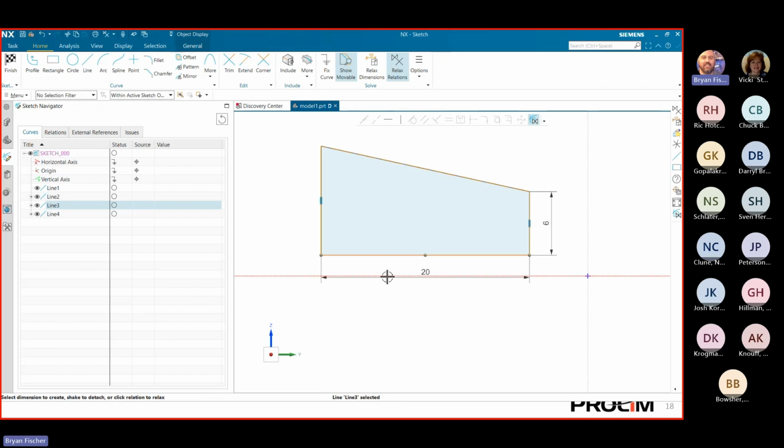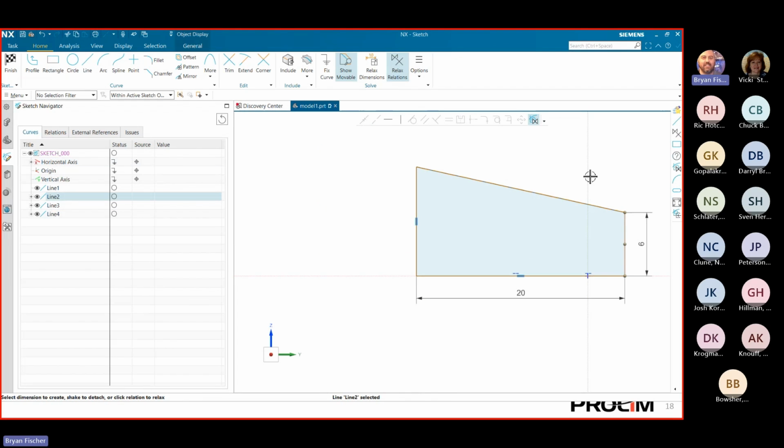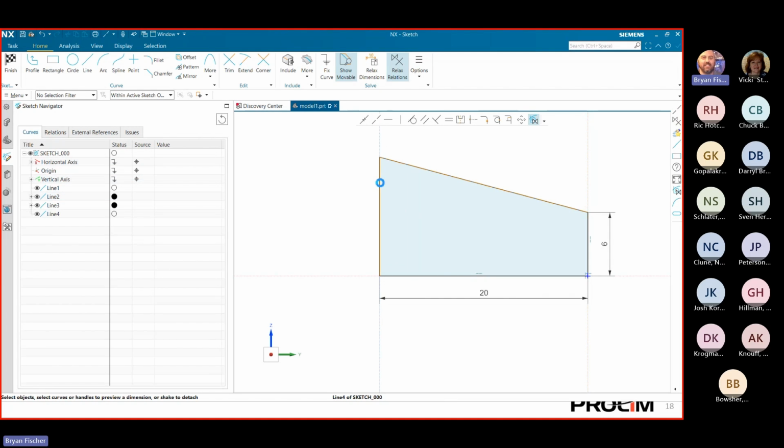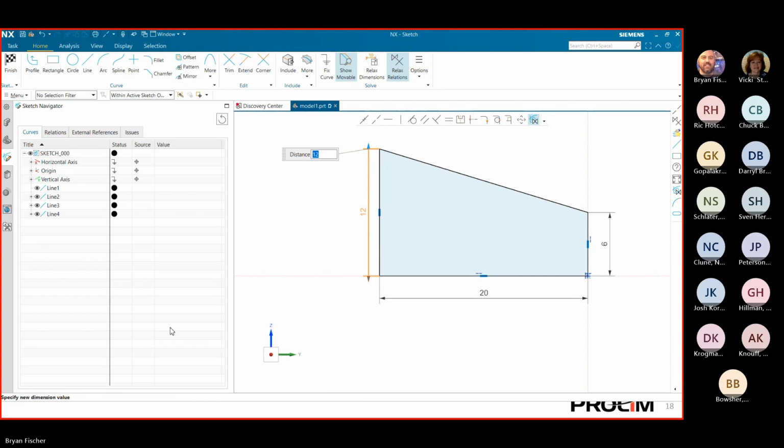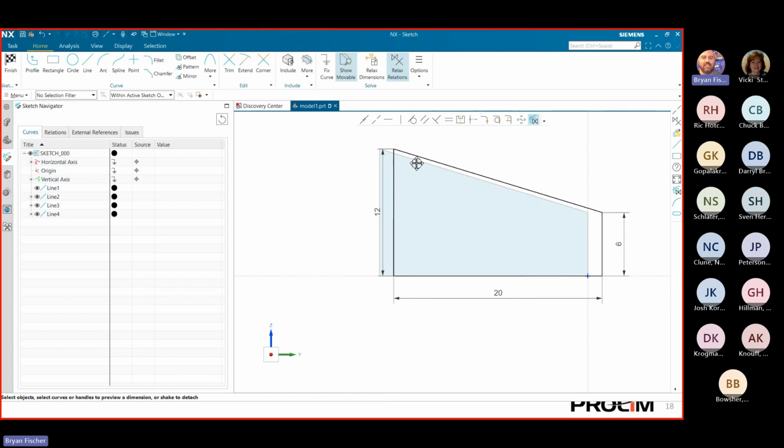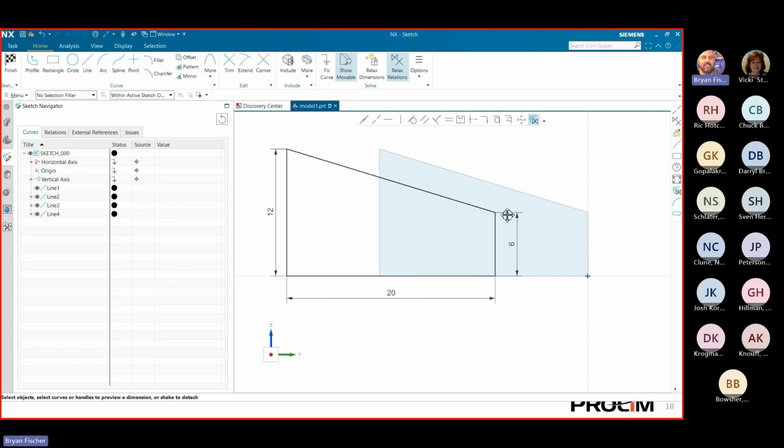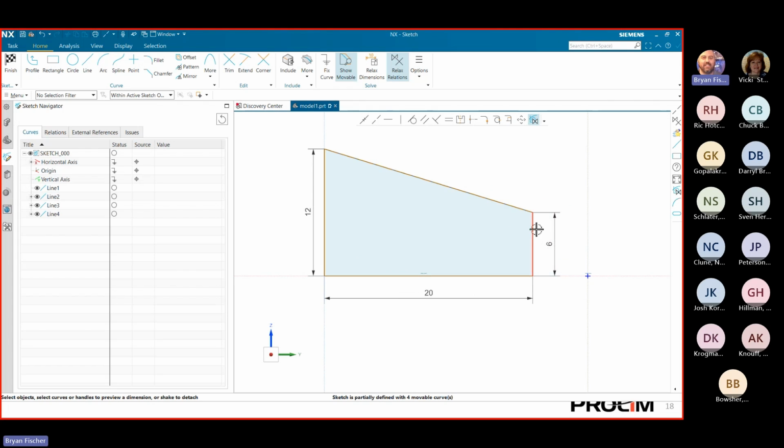Right now, for example, I'll go in and make this one fully constrained really quickly. Well, it's not even fully constrained anymore; they call it fully defined. You see how quickly I did that, and now these are all black, and I can't move any of this stuff, see, it won't let me. It'll let me move it this way because I have a dimension on that.